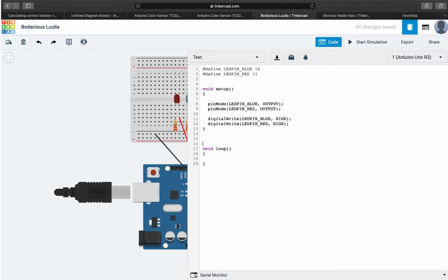In our case, we can have a function called transitionToBlueState, and another function called transitionToRedState. In here we will define every little thing that will happen whenever we transition to the blue state, and every little thing that will happen when we transition to the red state. And then inside our logic in the loop, whenever we want to transition, we will just call these functions.